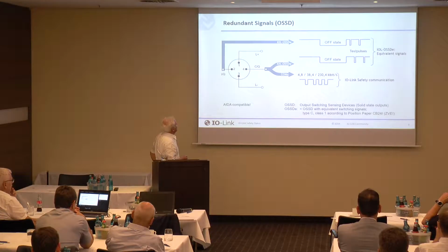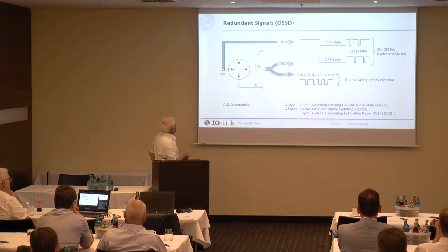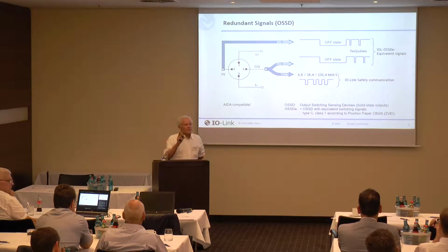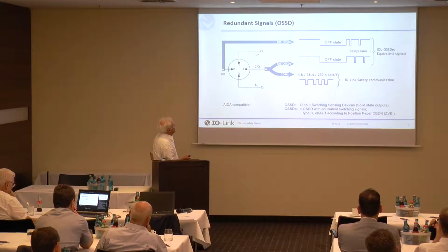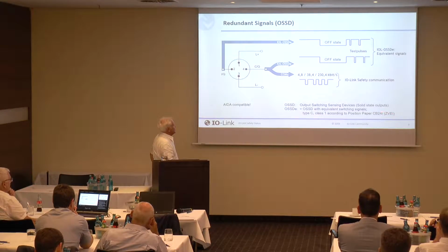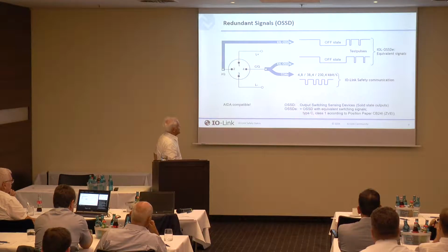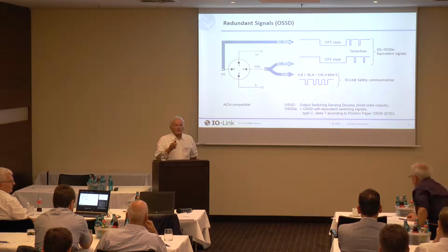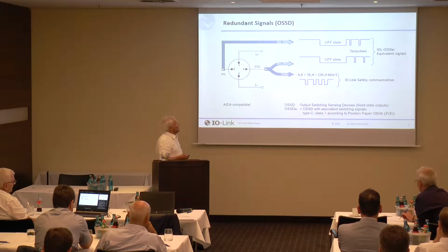So OSSD, what does that mean? We do not have only one signal here, like in standard IO-Link, switching and communication. We are using this free pin 2 for this second redundant input signal. And here we are working closely together with ZVEI. They have a position paper, and we are standardizing our OSSD solution to Type C class 1, which is classified in this ZVEI paper. And this, I was told, is 80% of the market.